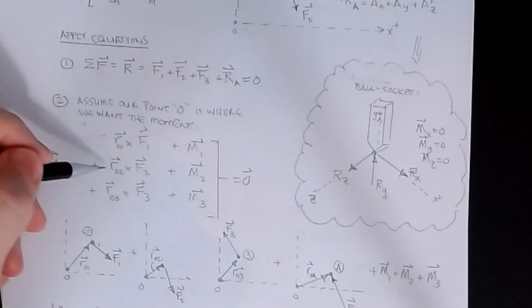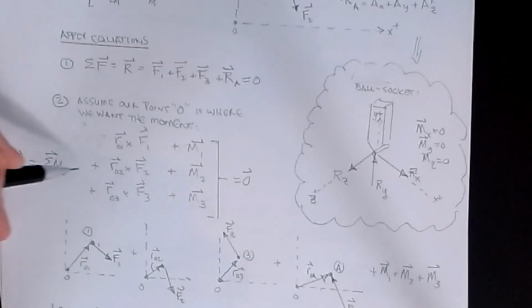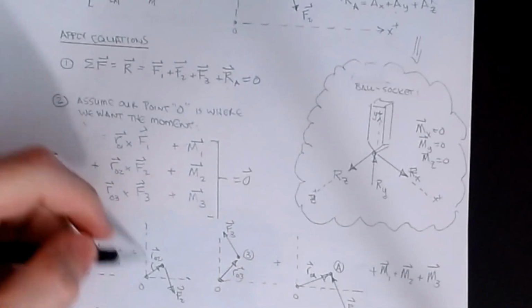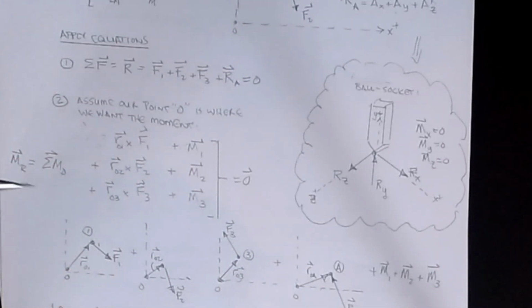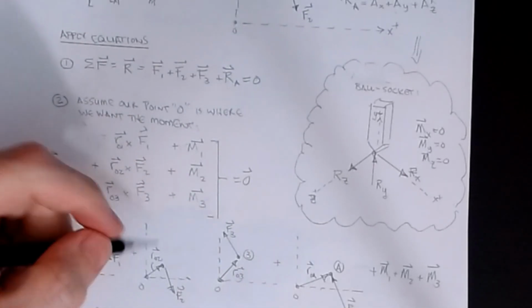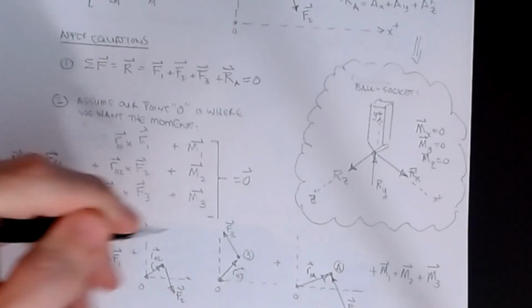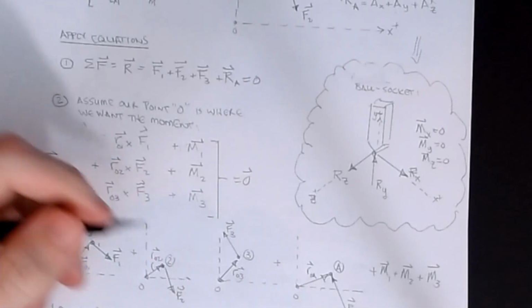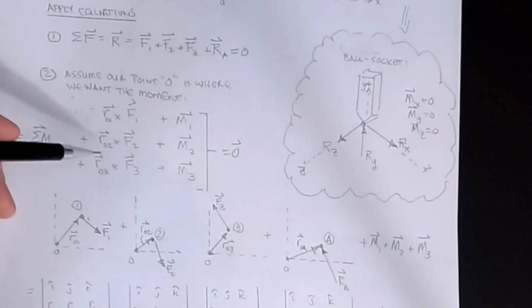So now we go to the second one, and for the force at 2, I need an R from O to 2. Okay, and so if I look at that, then same object, my F2 on that picture was acting kind of downward. Again, I don't care about the signs. These are just vector equations. It's one of the beauties of working with vectors. All right, and so then R from O to 2 goes from O up to 0.2. That would be this point here, and that's the vector. And so again, if you know the coordinates of 2 and the coordinates of O, you can find that position vector. And that gets me that one.